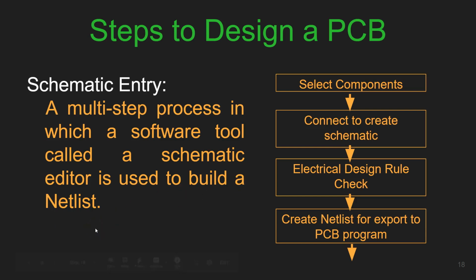A netlist is basically a simple text file, and you can inspect it with a text editor. When you open that file, you will notice that the file contains all the information the PCB layout program will need in order to know which components are supposed to be included, what the connections between those components are, information about the nets, and so on.